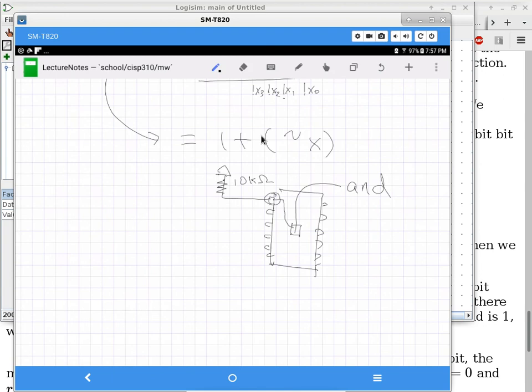But if you use a pull-up resistor like this, and for whatever reason you soldered the wrong chip, for instance, or the chip itself has gone bad and you want to ground everything possible, at this point, it's not going to hurt anything, because that connection is going through a 10k ohm resistor. If your supply voltage is say 5 volts, then you're really talking about less than a milliamp going through the whole thing. It's not going to hurt anything. So all of these are for safety purposes. You put in the pull-up resistor. You do not leave anything unconnected.